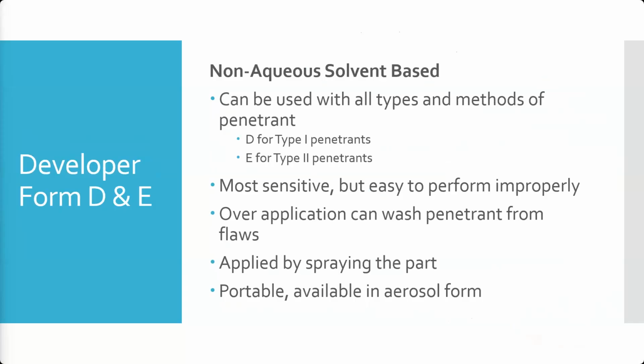Right? I don't want to sit here and press the button. That'll leave a big circular blob of material that's way too thick and it'll hide our indications. So you want to do nice passes, even around the whole part, never starting or stopping your pass while pointed at the part. Okay, so it's just like you learned in structures painting class.